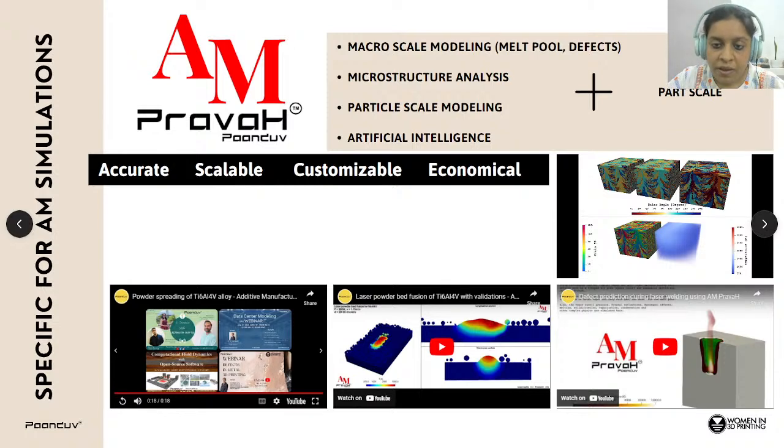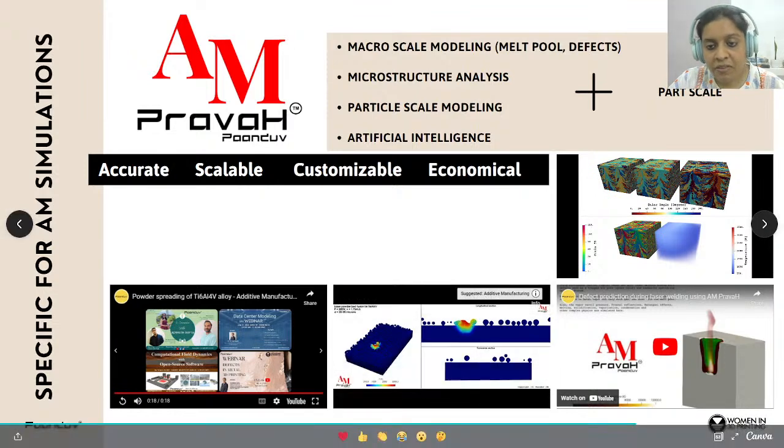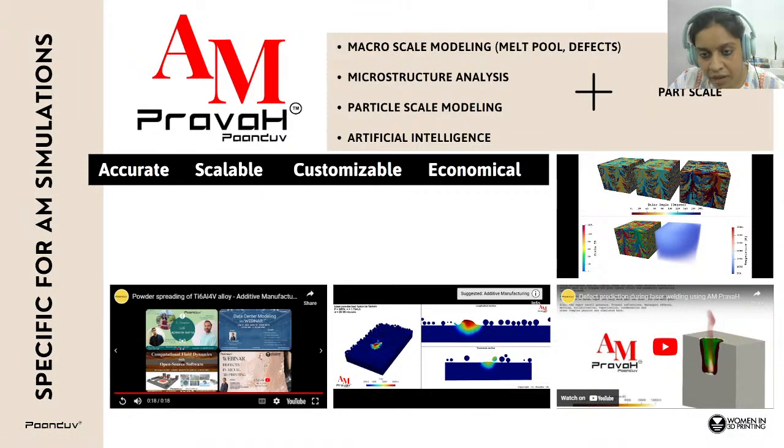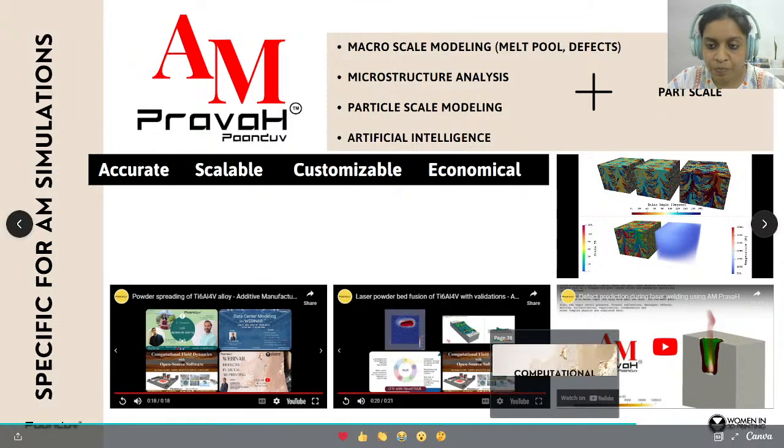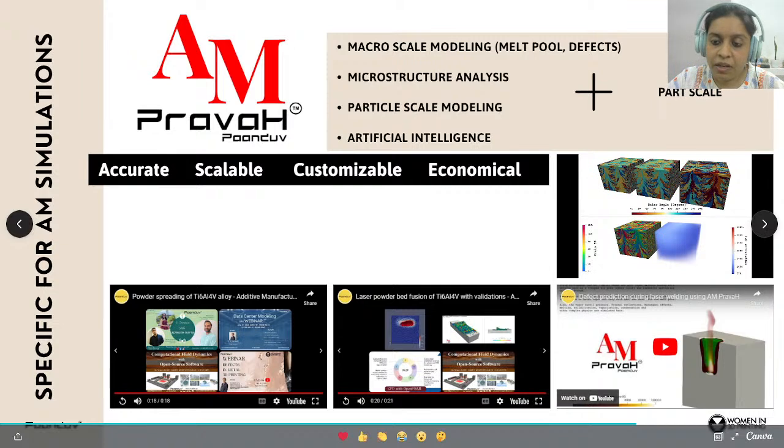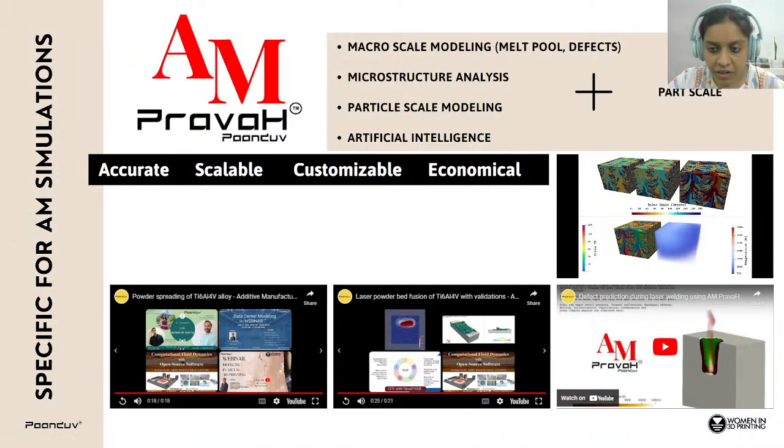powder bed. The second one is related to the melt pool dynamics. The laser is moving in the positive X direction and you can see the temperature distribution of the melt pool, and the right-hand side cross sections show you how well the Marangoni effects are observed here. This is exactly like the dancing melt pool. The third one will give you a clear idea on the defects.